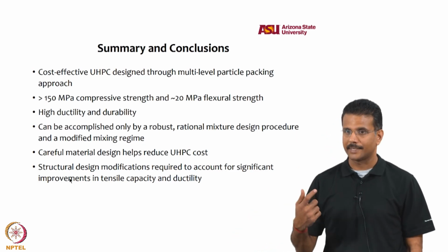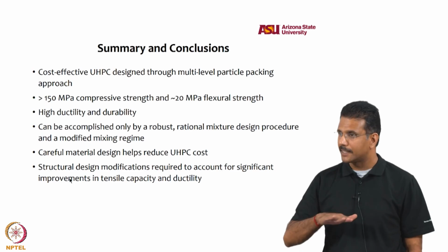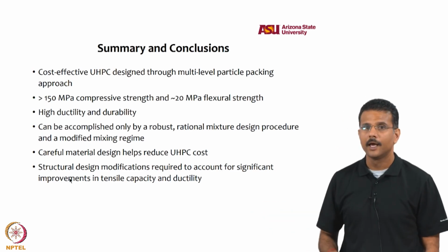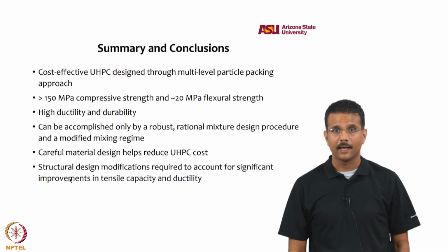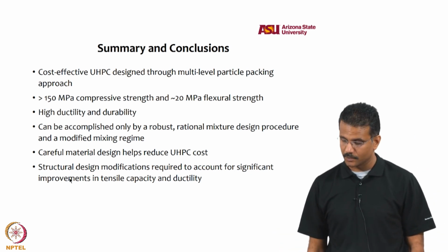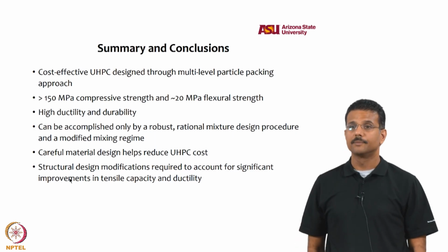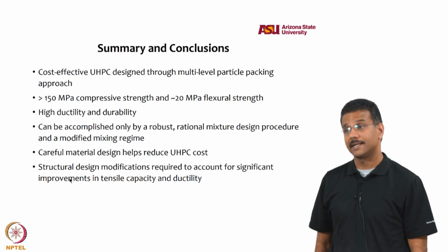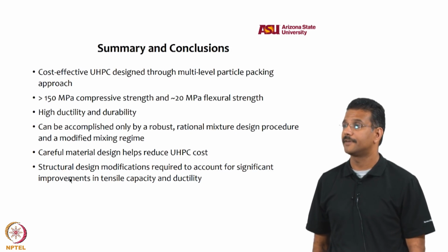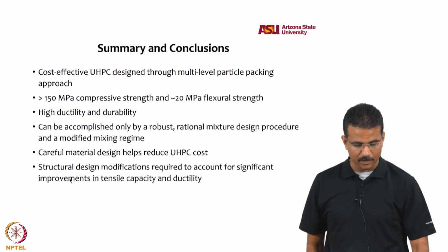Water cement ratio is that which is required to make this thing flow and fill. You have to have careful material design to ensure it is economical, and then structural design modifications to account for significant improvements in tensile capacity. It is the tensile capacity and ductility that makes this material very different from conventional concretes.